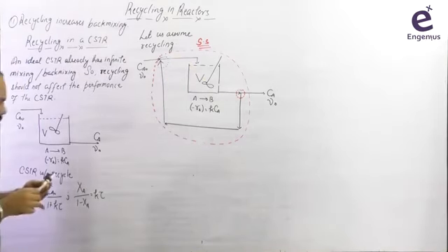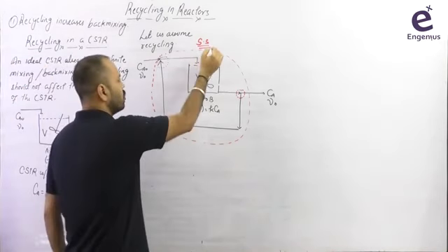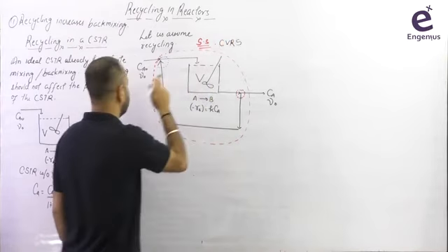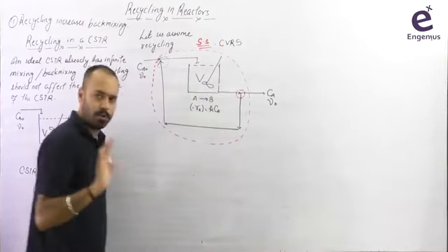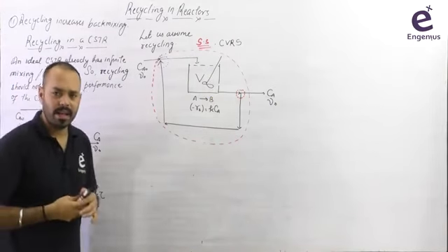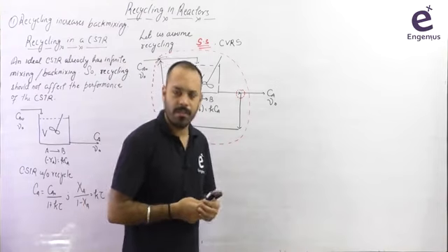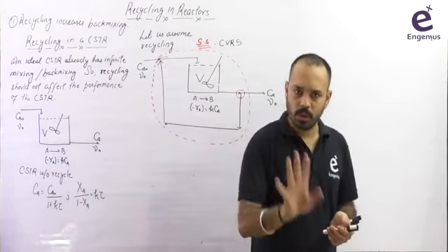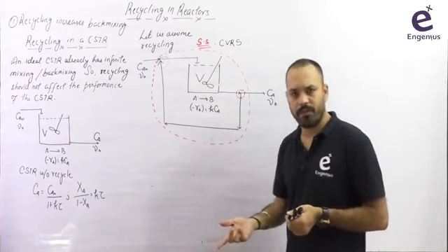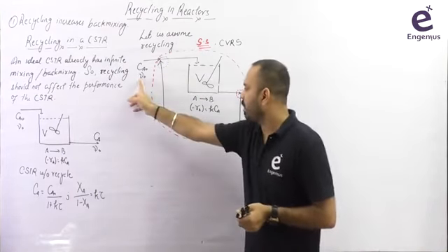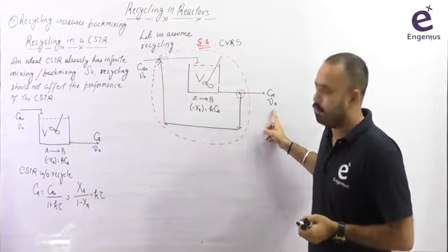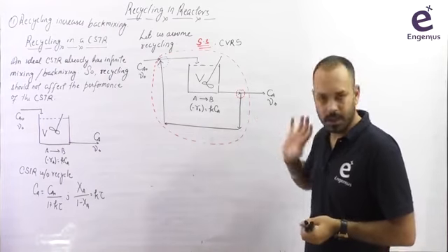Now we are dealing with steady state system and we are dealing with constant volume reaction system. Now if you are saying that, sir, this nu naught and this nu naught should not be same, you are wrong. The thing is it is constant volume reaction system. At constant volume reaction system, you know that the inlet and the exit volumetric flow rate should be same. And if I am not taking these volumetric flow rates to be same, then definitely there will be accumulation inside the system, because it is CVRS and it has to be steady state also.